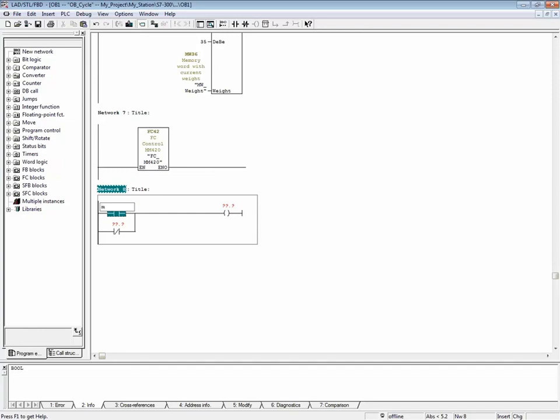Select the first contact. It is commonplace to use a memory bit that ends in 0.1 for an always on bit. So let's add M0.1. Type M0.1 over the closed contact also, and over the coil. If M0.1 is true or false, the coil will be true, so the bit will be always on.